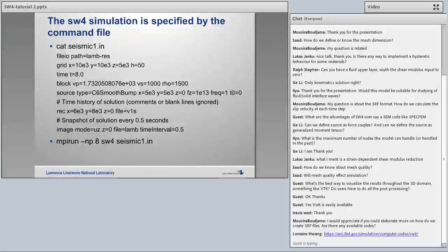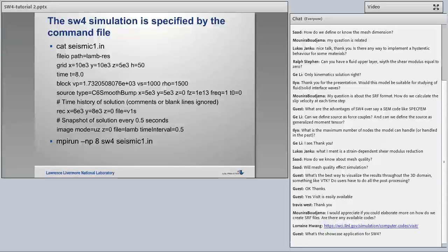The advantage of SRF files is that the whole rupture is described in one file, separate from the input file. Previously, you had to put all the discretization of your extended rupture in the input file, so the input files became rather long. But using these SRF files, this should be avoided.